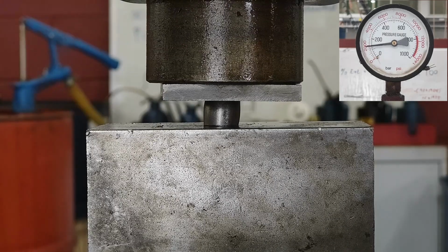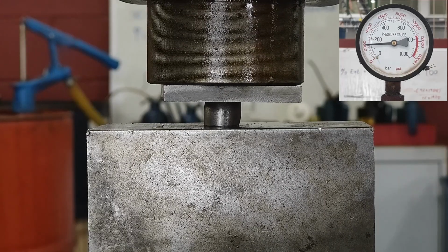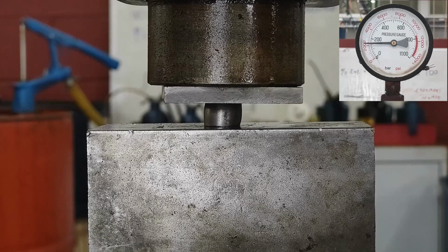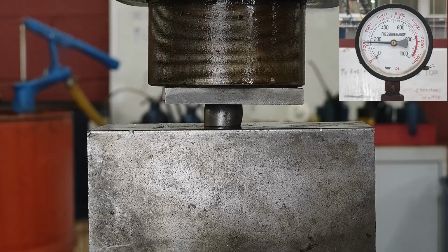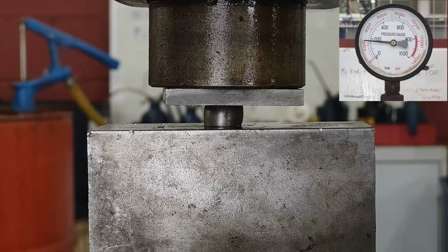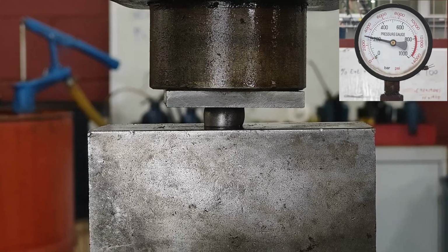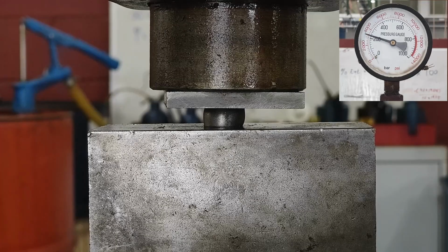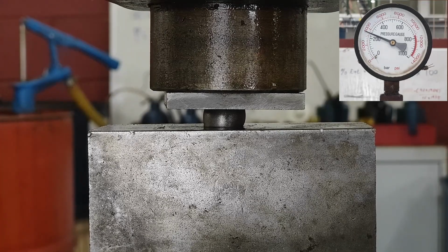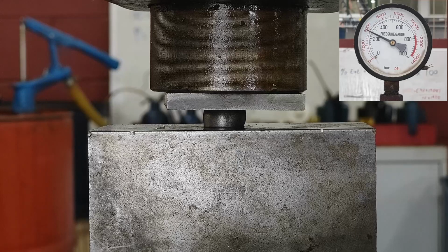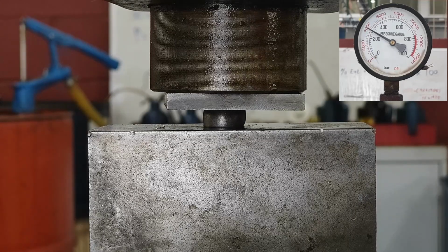As the mild steel specimen is compressed, it begins to bulge outwards on the sides and becomes barrel-shaped. With increasing load, the specimen is flattened out, increasing its cross-sectional area, which increases the resistance to further compression. This is a clear indication of malleability, which is expected as mild steel is known to be a highly malleable and ductile material.